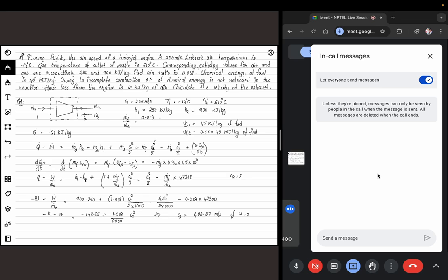so basically if we assume that this turbojet is not rotating any shafts, which is usually not the case. The turbine shaft has to be rotating your engines with the energy being generated. If we neglect that part, then if W equals 0, the exhaust velocity will be 488.87 meters per second. But if that's not the case, that is, you're generating some power from this turbojet engine, then you will have a certain value of W.